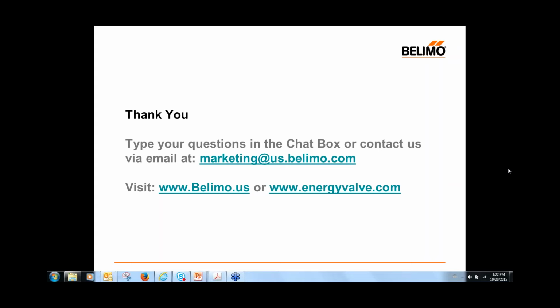I see some coming through. So I'm going to read the first question. What does the Delta T Manager do? The Delta T Manager looks at a programmed or entered set point value for the delta T between the entering and leaving water temperature of the air handler's coil. And if we go below that value by 2 degrees for 5 minutes, it will incrementally reposition the valve to raise the delta T across the coil and then release back to normal TDC control.